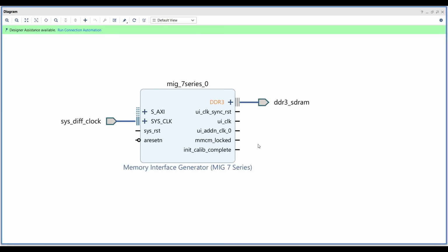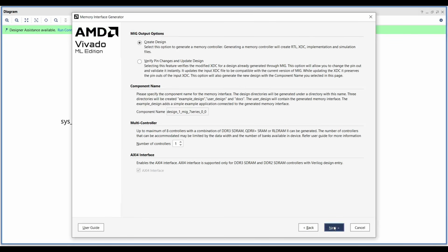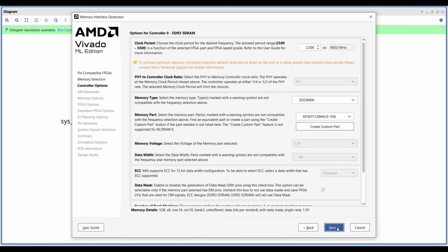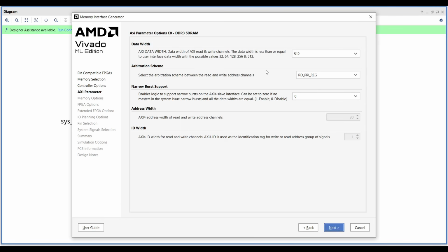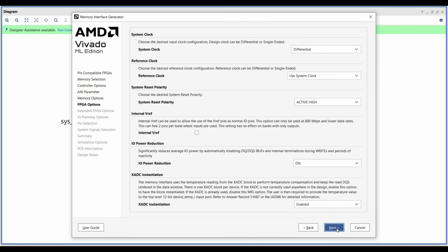As you can see, Vivado automatically connects the MIG to the right pins for me. If you also open the MIG, you will see that Vivado automatically configured it based on the datasheet and the user manual of the board. If I wanted to do all of these steps manually, I would first need to carefully study the user manual of the AC701, and also set up and configure all of these clocks and options carefully. But here Vivado took care of all of these difficulties for me.